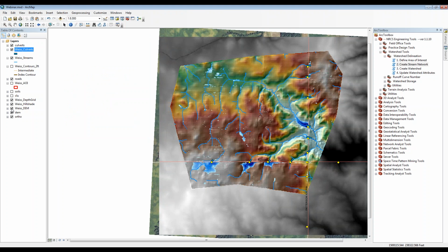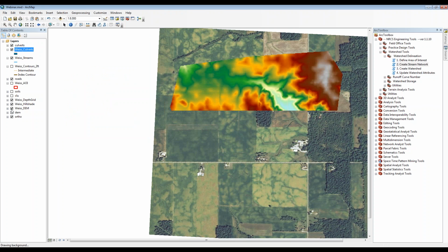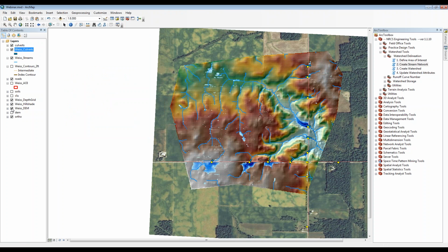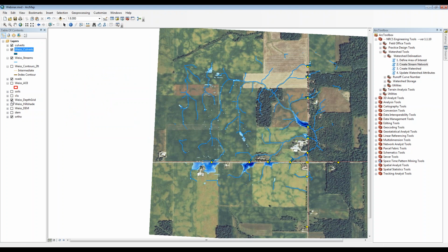We've got a lot going on our screen, so I'm gonna start turning a few of these off so we can see what's happening a little better. Okay, like I noticed before, up here I'd like to see more stream networks going away from our watershed. We might end up clipping a little bit of our watershed in here, but we'll cross that bridge when we get there. Okay, we have our stream network. This is the outlet I'm interested in. We're gonna redo this waterway.